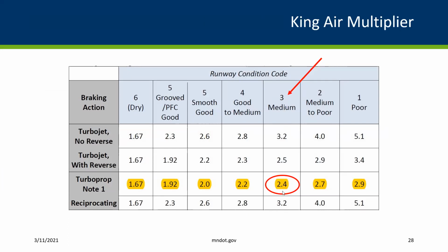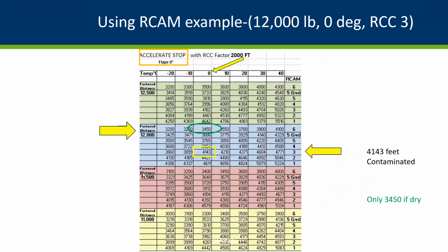This does include from the approach end of the runway your flare, and the runway that you're not touching down on. So this is your flare out also that's incorporated into these distances. As you can see here, even on a dry runway, you multiply your ground roll times 1.67, and that's to account for the safety factor as you fly in, round out, touch down, and then brake.